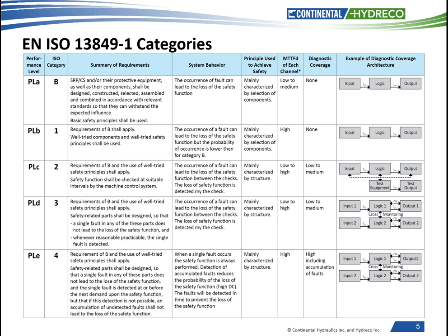The components selected must be suitable for the application, correctly specified voltage, current, environmental condition, sizing the component correctly for the flow and pressure being used, and also ensure that we use well-tried industrial components and circuit principles. That must be part of the design.